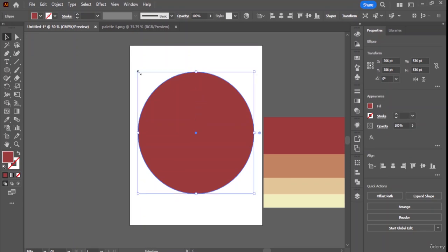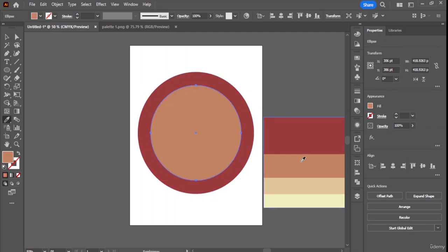Now we already have another one. Now you will see that there's another circle, but what you're going to do is press Alt and then Shift so that you get an exact size circle from the exact place you are trying to make it from. You can see, Control Z. I'm going to press Alt, Shift, and then get your exact size. There you go. Then I'm going to change this color into this one.